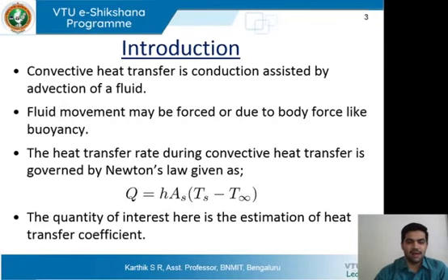So in either of these heat transfers, you have to recognize that there is a solid surface upon which there will be a fluid which will be moving. Now the heat transfer rate during convective heat transfer is governed by Newton's law of cooling, which you are already familiar with. It is given by hA(Ts - T infinity), where Ts is the surface temperature in this case. We are assuming that the surface is at a higher temperature than the fluid, but the vice versa is also true.